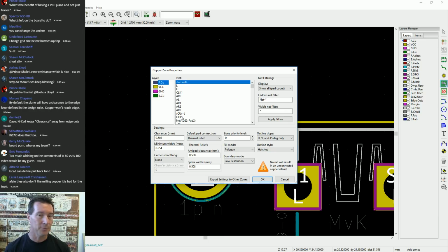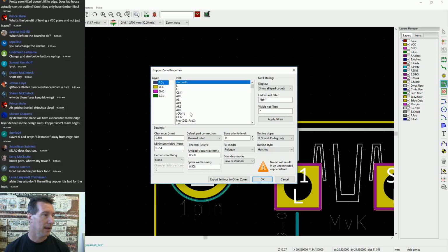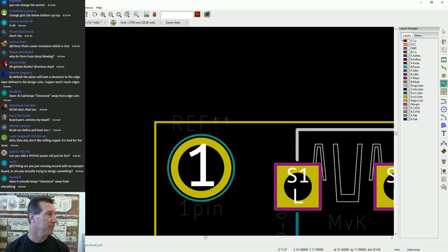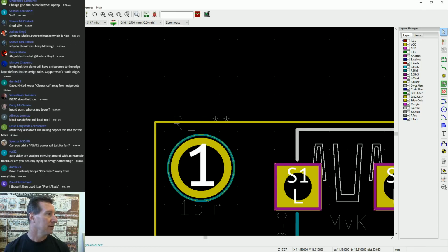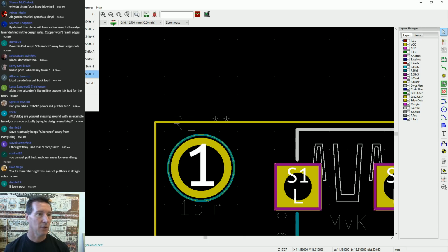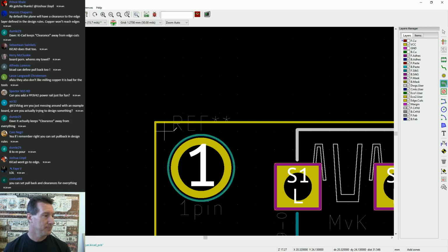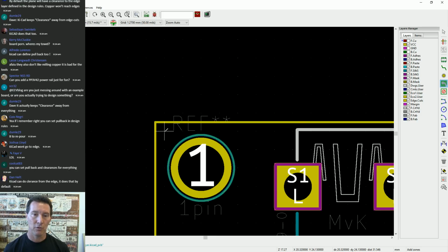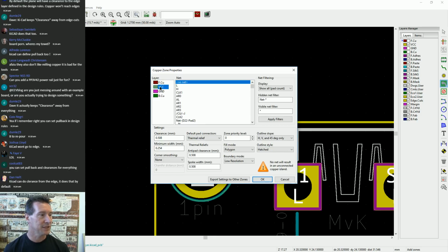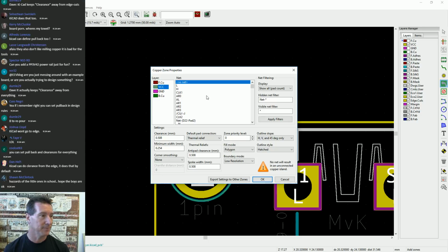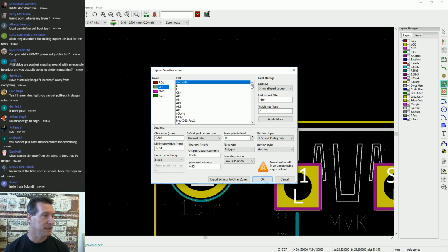All right, so what we're going to do is place a zone, and we're going to pull back from the edge. We're going to select the layer we want, VCC, which is our power, and then we select the net that we want.